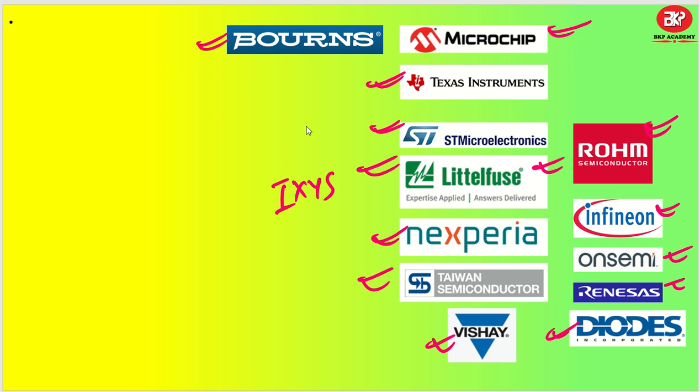Okay, so with manufacturers in mind, you can now proceed to select a diode. Why? Because these manufacturers are the ones which are going to affect you maybe 10 years from now. Let us say you have selected a part A from, let's say, Nexperia. If you select from the local market or local companies, after 1 year it may get obsolete or be removed from the shelf. That's the reason we always prefer standard companies which have standards of manufacturing, and they promise to keep a particular diode or component available for a longer amount of time.